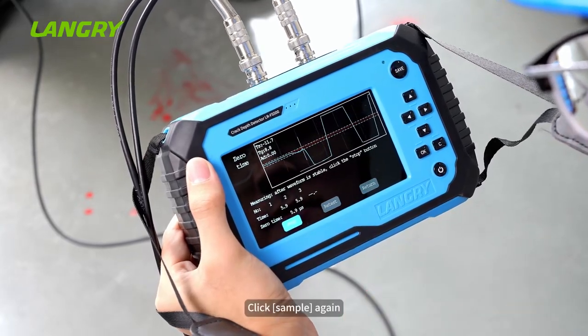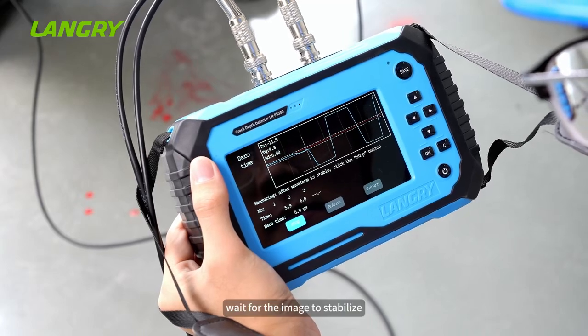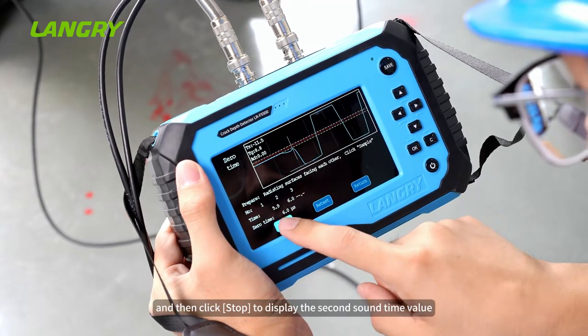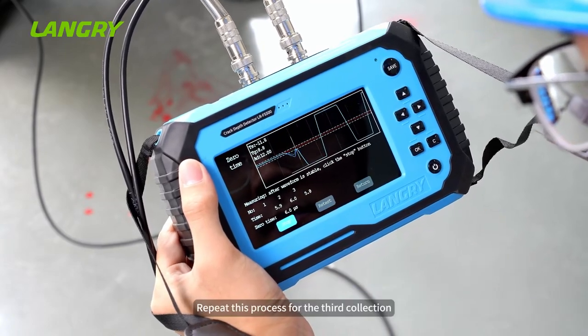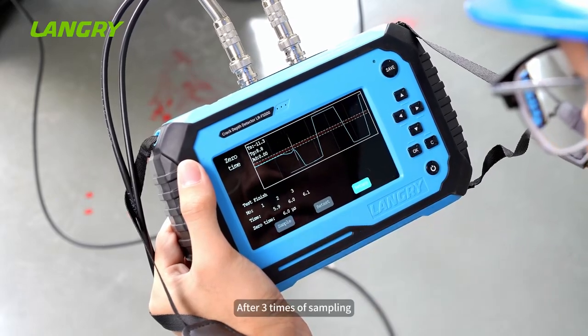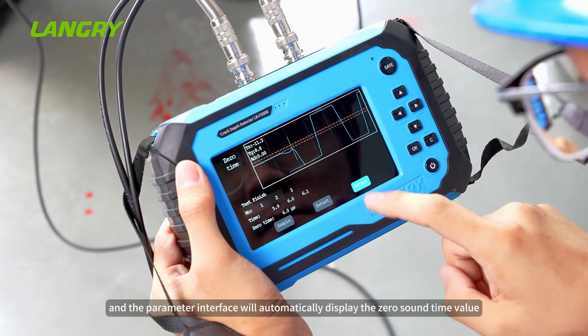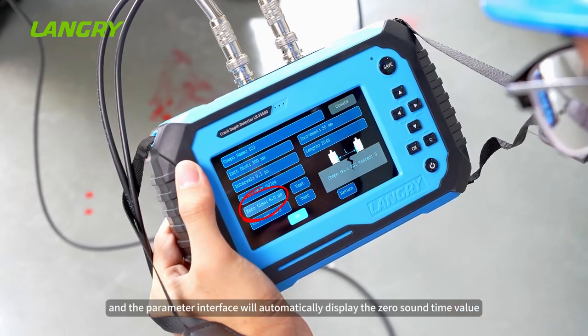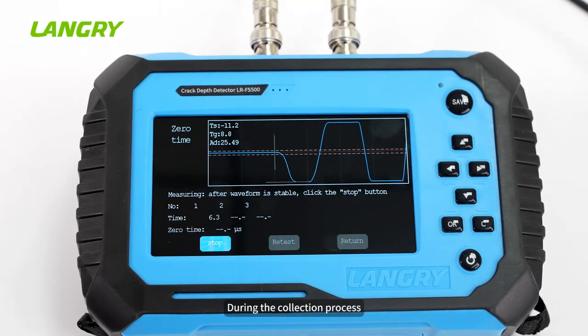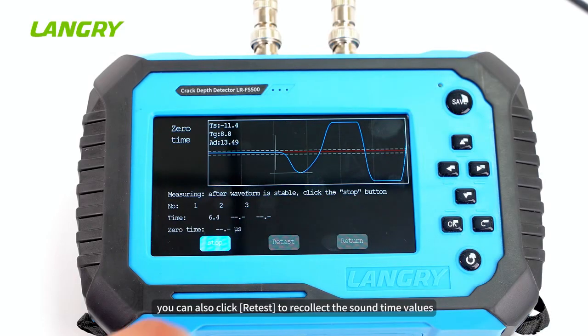Click Sample again, wait for the image to stabilize, and then click Stop to display the second sound time value. Repeat this process for the third collection. After 3 times of sampling, click Back, and the parameter interface will automatically display the zero sound time value. During the collection process, you can also click Retest to recollect the sound time values.